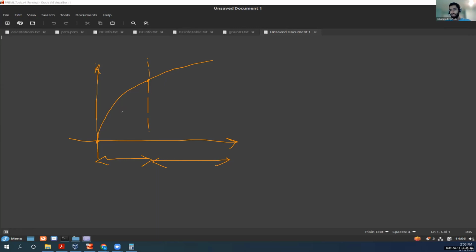So there are Newton-Raphson iterations. What Newton-Raphson iteration does is you have an initial guess, and then you define the residuals based on this initial guess. From this initial guess, you would define stress and strain, and from this, you would define the residual.